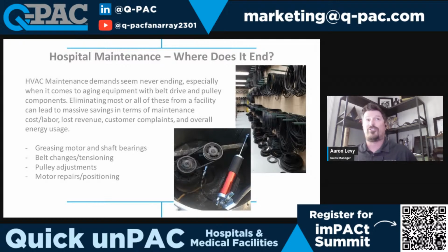And with the Q-PAC system, we can eliminate a lot of that from a facility, and it'll save them in terms of their maintenance cost every year for their labor and for the components themselves. It saves them from lost revenue because once a system's down, a lot of these belt drive systems, if you ever lose the shaft or a pillow block bearing, or even the motor, sometimes they're not just readily available sitting on the shelf, and you could be down for a few hours to a few days, depending on how long it would take you to install those components. Then you obviously have customer complaints, and then of course their energy usage. They do tend to be energy hogs.